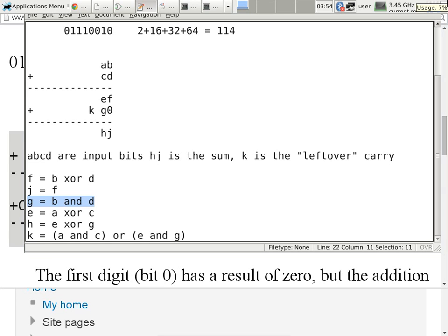So this is what your homework assignment should look like. You have a single half adder all by itself, because it's a 0 here. Alternatively, you can turn this into a full adder too, except the input becomes just a constant of 0. You can specify a constant of 0 in the schematic, which will just be wasting some gates, but it's okay too.